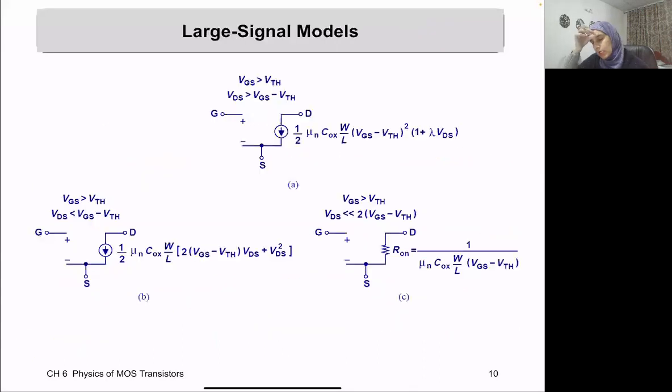So now we basically want to study the behavior of this transistor as an amplifier. And since they are nonlinear circuit elements, we need somehow to look at a portion of its operation that we can, in this small range, consider as linear, if this is possible. And in order to do that, there are two models that help us. The first is called the large signal model, and then we have the small signal model. The large signal model is basically useful to decide the operating region.